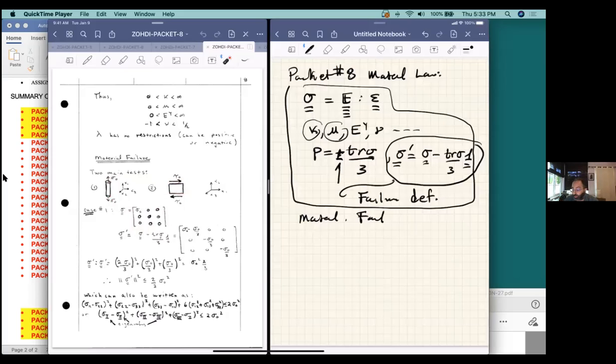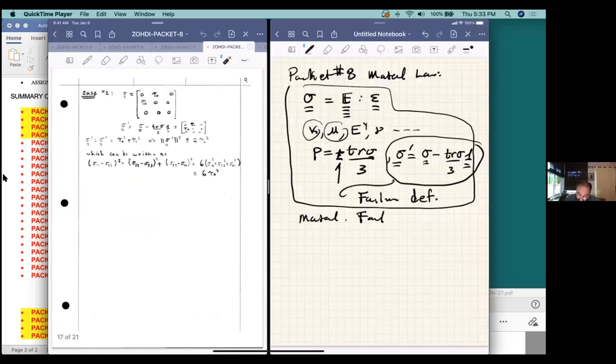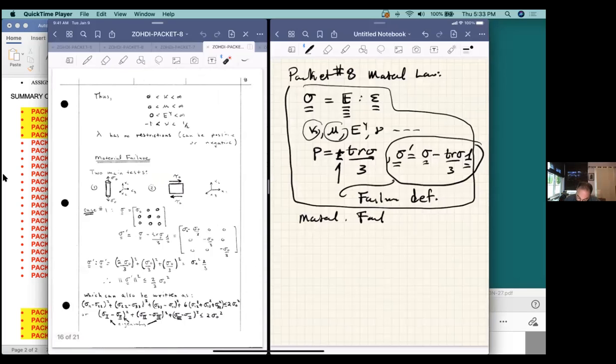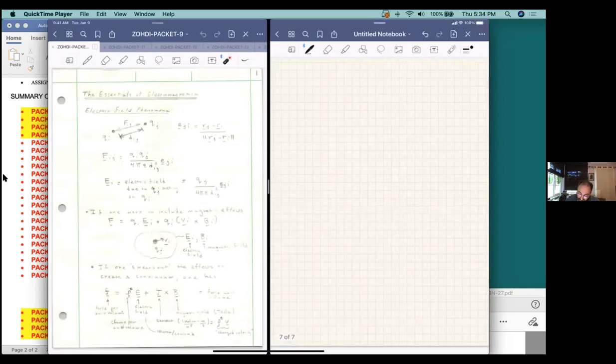Of course, almost all of the subsequent failure analyses that are a little bit more complex build upon this sort of building block of the von Mises criteria, which is shown here on page 9 and also on page 8. So again, depending upon how you've seen it portrayed as an undergraduate, the formula for the von Mises criteria can really be boiled down into a much simpler case here, which simply says that the norm of the deviatoric stress has to be less than 2/3 sigma 0, where sigma 0 comes from a simple one-dimensional test. So that's important because then you don't have to remember all that crazy stuff from all the formulas. Of course, after a while you can't forget them, but generally speaking, the formulas there can be boiled down to something pretty straightforward in this regard. So that's packet number 7, 8, 9.